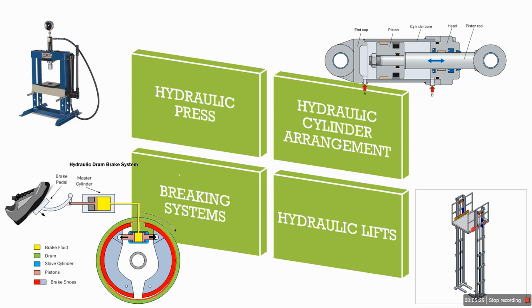Then I have braking systems. In braking systems, we use the basics of Pascal's law. If I'm applying the brake pedal on one side and deflecting the piston, that piston will ultimately result in application of force over the fluid, and using Pascal's law, that fluid pressure will be generated throughout, and I'm getting a different force at the other end to drive the brakes, the disc brakes in there.